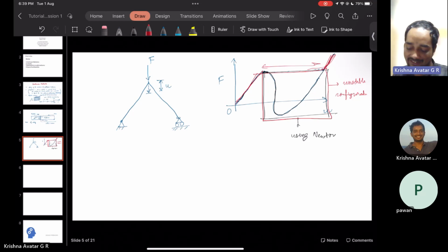This jump is what we often call, in structural mechanics, bifurcation. It starts here and jumps very fast with very fast dynamics. Essentially our system is bifurcating from one state to the other, and in books this is typically referred to as snap-through bifurcation, since it's snapping from one stable configuration to the other.